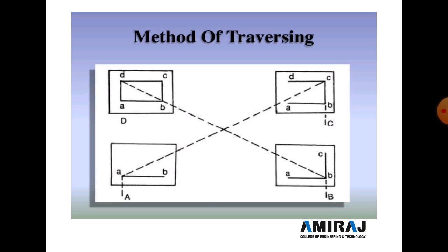Then using the U-frog plumb bob we mark the capital A point as small a on the paper, then touch the alidade at the point and bisect the B point ranging rod. Clear? So fix the ranging rod at B, bisect it from A, and then draw the line.